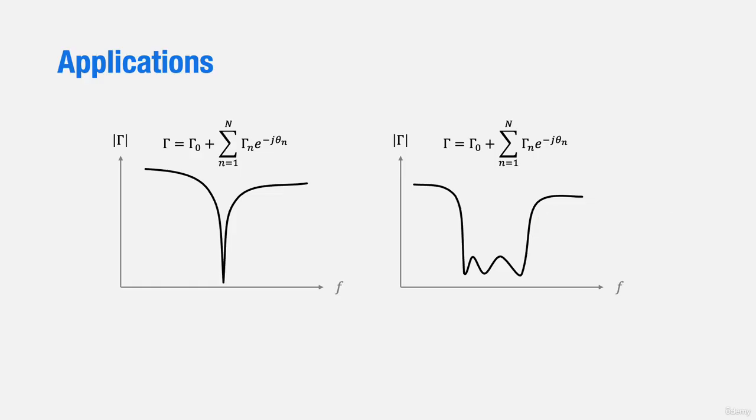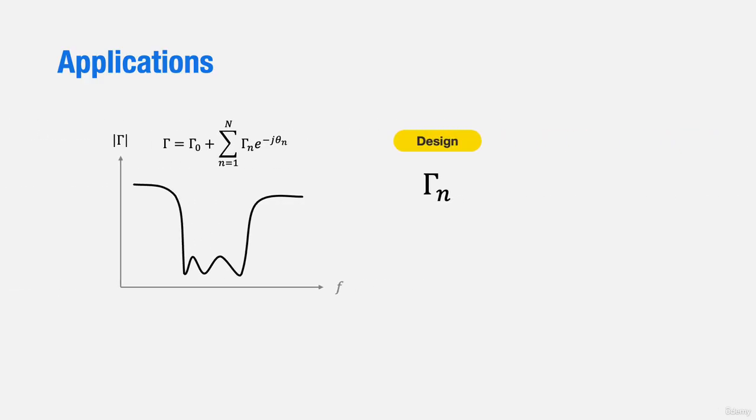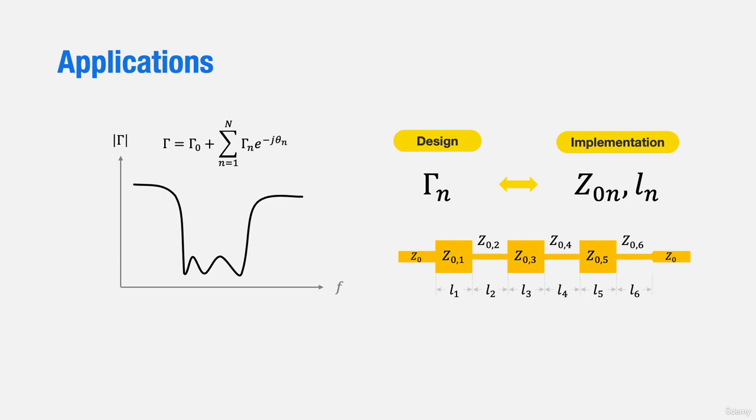During the design phase, engineers are primarily concerned with the reflection coefficient gamma, as its frequency response is our design target. By cleverly using mathematics, we can create the curves of gamma's frequency response. Then we must translate them into practical circuit parameters such as line impedance and length so that they can be implemented into the circuit. But the use of transmission lines doesn't stop here.